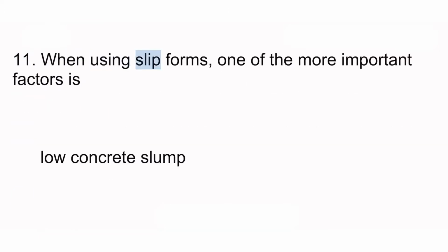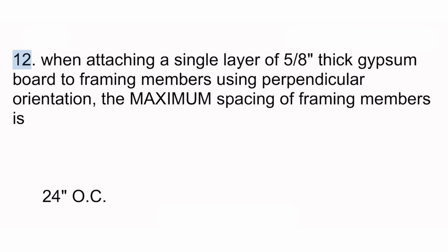11. When using slip forms, one of the more important factors is low concrete slump. 12. When attaching a single layer of 5/8 thick gypsum board to framing members using perpendicular orientation, the maximum spacing of framing members is 24 OC.